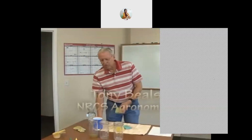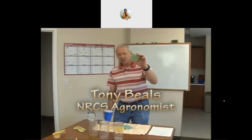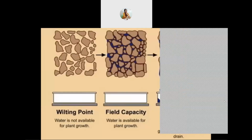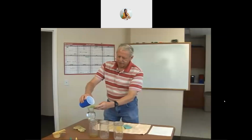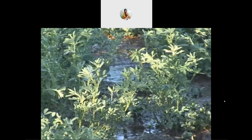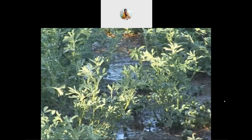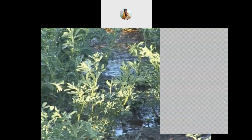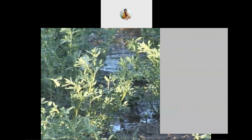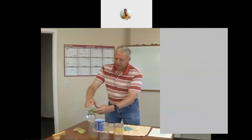We're going to demonstrate field capacity. Now, I mentioned to you before that field capacity is when the soil has all the water it can hold under the pull of gravity. Okay, so now we're going to add some water to this sponge, a little bit at a time here. So now we're irrigating. This is what you would do when you're irrigating, only you would want to calculate how much water you need to apply, and you need to understand how much water your irrigation system puts on, etc.